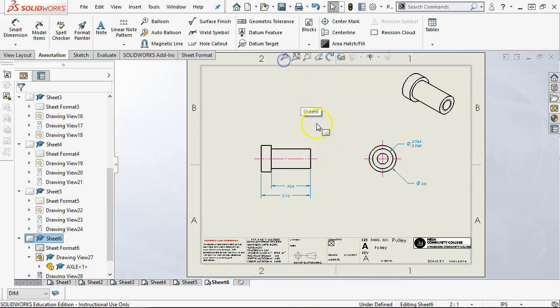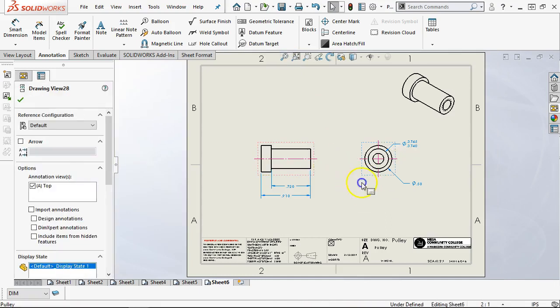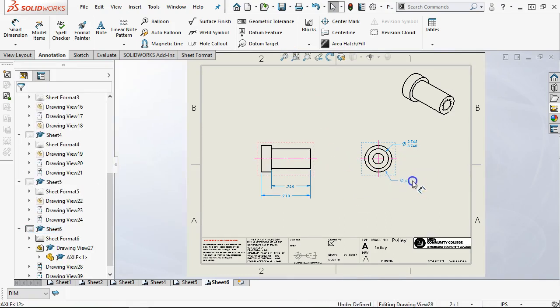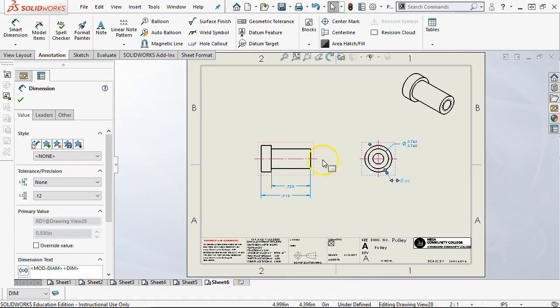All right, that may not play out, but that also brings it to where when I go to inspect this, I'm not having to set up. And because this isn't my rotating piece, I don't have to worry about runout or total indicator runout. We're just going to ask, is this a cylinder enough to fit through the plate, through the bearing, through the other plate, and be able to bolt this?